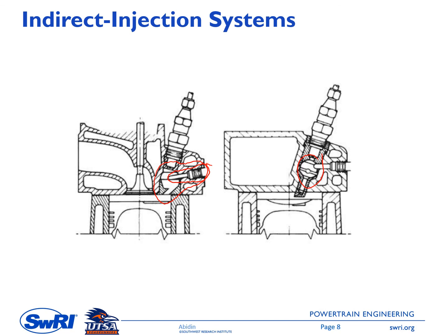But if you look back at the system on the left side, you'll expect to see a swirl flow or tumble flow, depending on which axis we use. So the flow will enter the pre-chamber, and I believe it will rotate like what I drew in the blue line here. But on the right side, the flow of the air will just enter straight toward the injector tip.